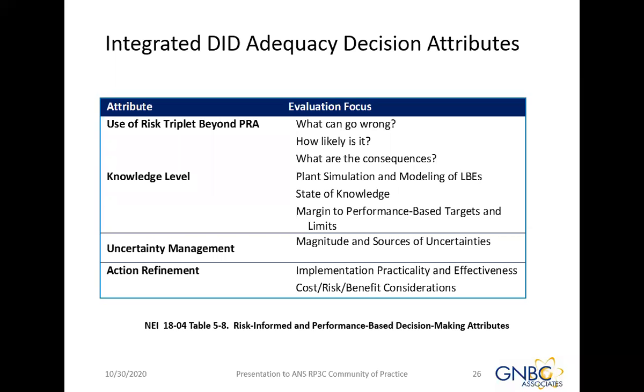And lo and behold, we discovered two things. One is it's really hard to melt it. And the second thing is, if all of the engineered safety features and everything else fail, your safety valves work. And so even if one of them doesn't work, or even if they stick open, which is the predominant failure mode, that's okay. The plant will not uncover fuel or melt fuel. So these are things that I think come into play, and you need to be attuned. And I think this process is intended to make sure people are attuned to this kind of process. I've talked about sources of uncertainties enough.